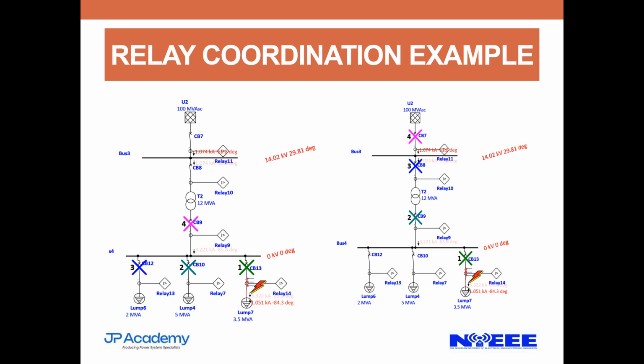As a protection practitioner, I don't think that diagram one is okay. I've seen in practice relays operating sympathetically, as a result of capacitive coupling between feeders, where feeder one operates and feeders two and three go with it. So that is bad and it's a no-no.